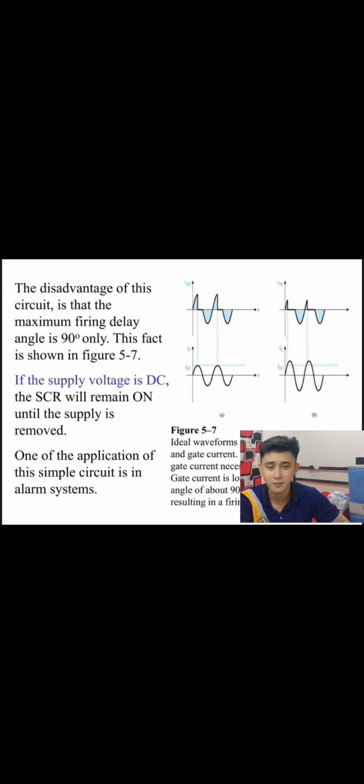So next. Disadvantages of the circuit: the maximum firing delay angle is 90 degrees only. The fact is shown in figure 5.7. If the supply voltage is DC, the SCR will remain on until the supply is removed. One application of this simple circuit is an alarm system, whether that's a fire alarm or anything.